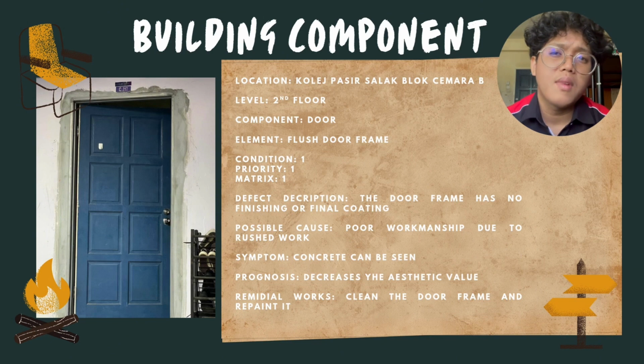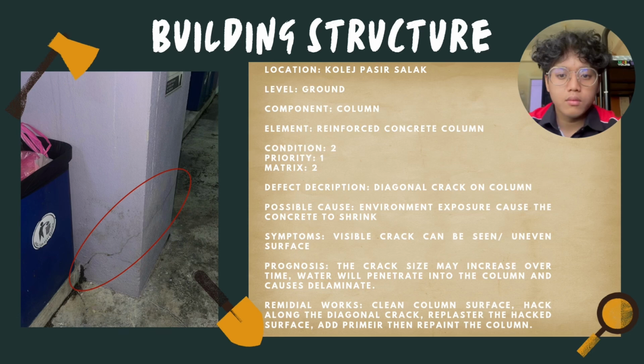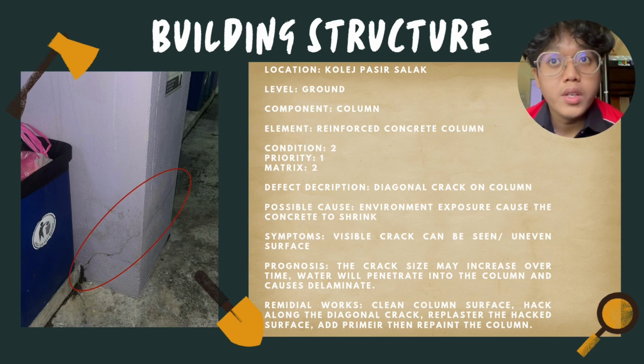The symptom is the concrete can be seen, which can cause the door to be less aesthetic. The prognosis is this decrease the aesthetic value, and the remedial work is clean the door frame then repaint it. Let's move on to building structure.